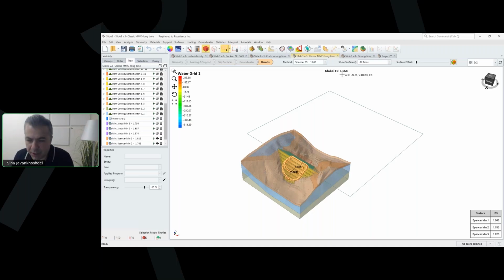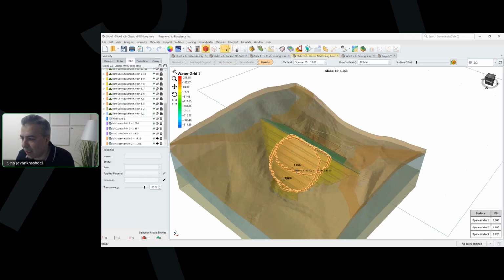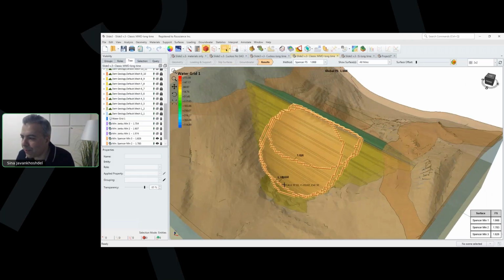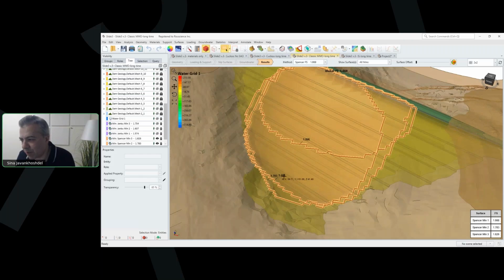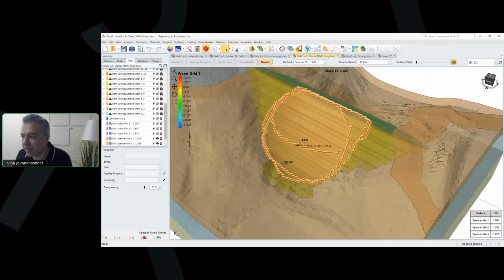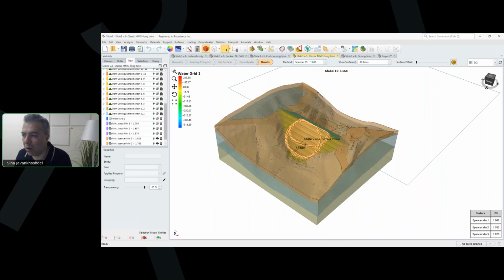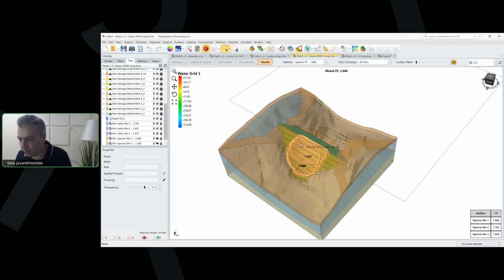So from no surface altering optimization to just cuckoo search and surface altering, and then multimodal, you can see how the factor of safety changed. If I zoom in, you can see factors of safety of 1.66, 1.78 and 1.82. These numbers are close with totally different failure surfaces. So multimodal optimization gives you all these. So this was for the simple dam model.